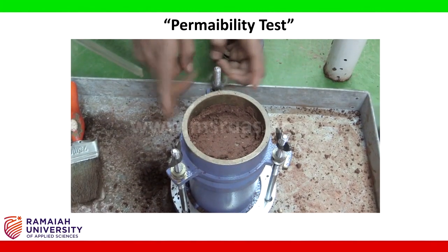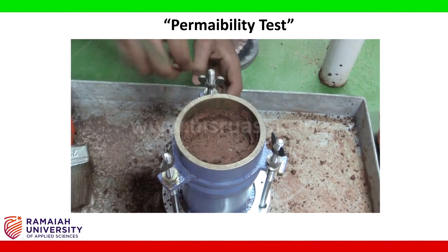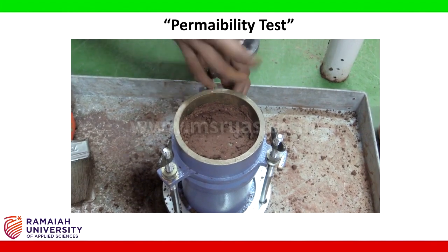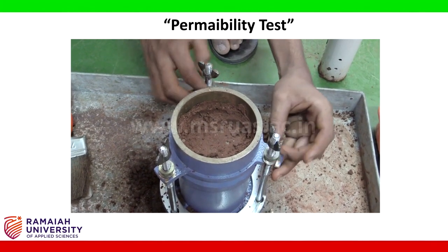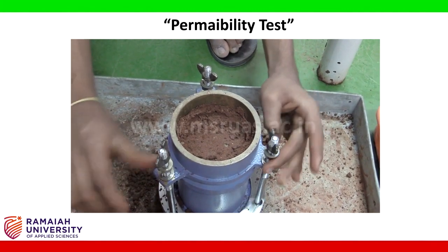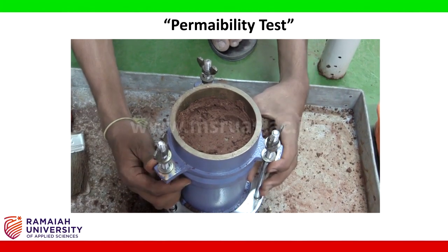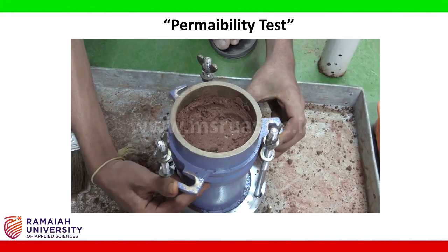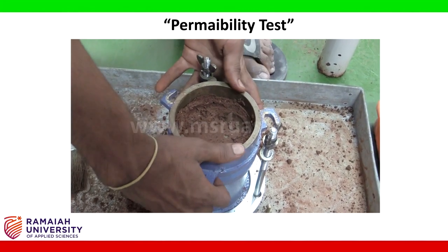Loosen the nuts like the way it is being shown, and gradually turn the collar and extract it out. Make sure the specimen is not disturbed.